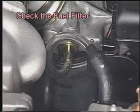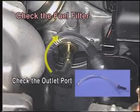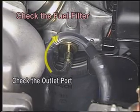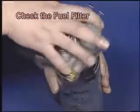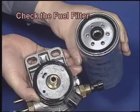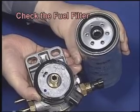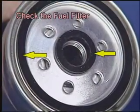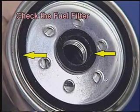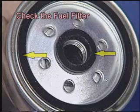As such, the fuel should be supplied to the outlet port in the filter so that the engine will work normally. In addition, you should check the inside of the fuel filter. To do so, check any tearing of the O-ring or any other defect that may result from air tightness. Furthermore, confirm if the rubber seal ring is functioning normally.